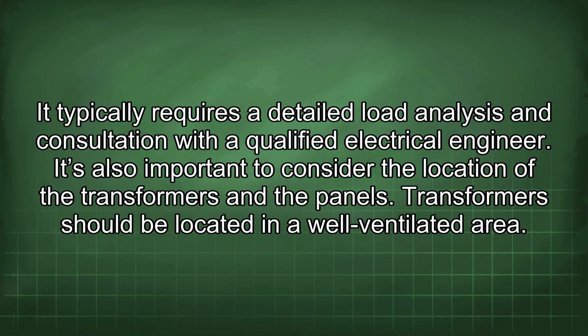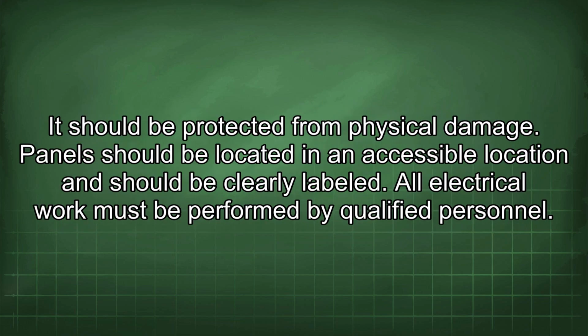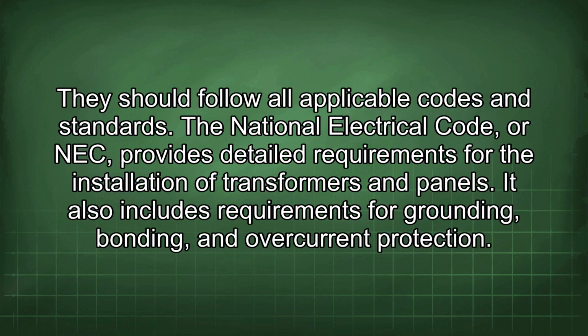It's also important to consider the location of the transformers and the panels. Transformers should be located in a well-ventilated area. It should be protected from physical damage. Panels should be located in an accessible location and should be clearly labeled. All electrical work must be performed by qualified personnel. They should follow all applicable codes and standards.